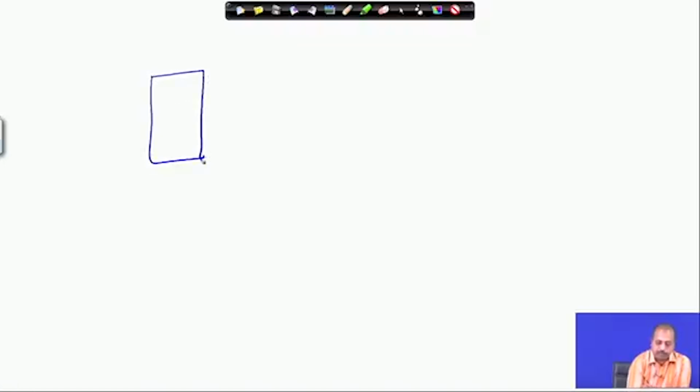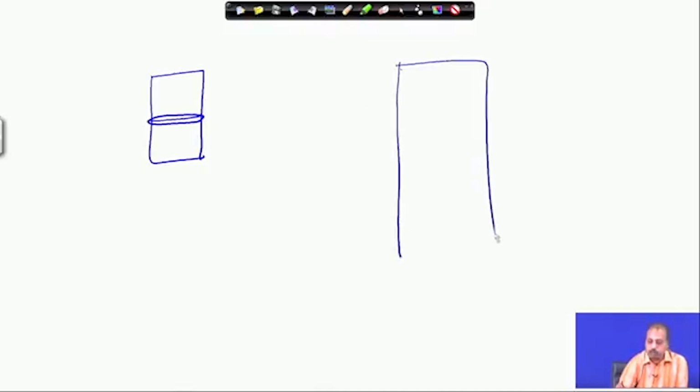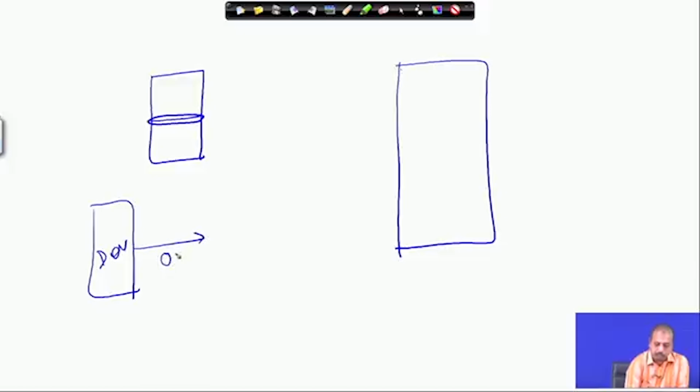Say this is the program at which the interrupt has occurred, when this particular instruction was getting executed. At that time the interrupt has occurred, so one RST code will be generated from the device. If this is the device, somehow this device will produce an opcode for the RST n instruction, and this will redirect the processor to some address. If this is the full memory.